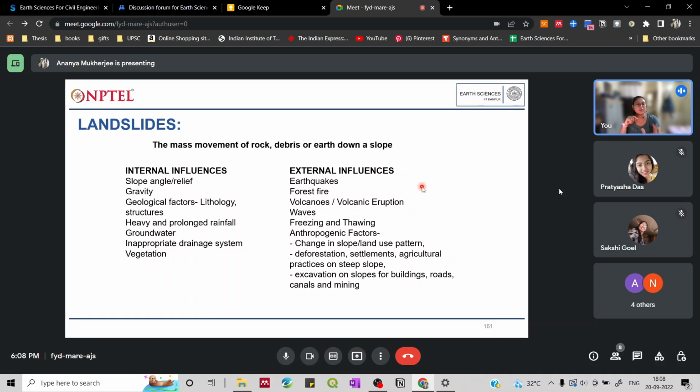They liquefy the soil around the landslide-prone areas, which causes the earth matter to slide down the slope and cause damage. And groundwater can affect this when it is mixing with the upper layers of the surface. It will liquefy the soil, and as you will see later, it can cause something called creep, which will eventually lead to loosening up of the material, and it could cause bigger landslides over time.